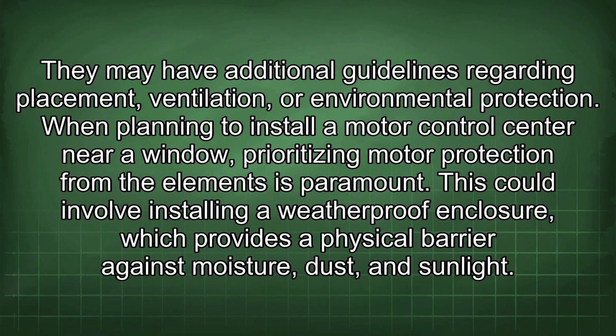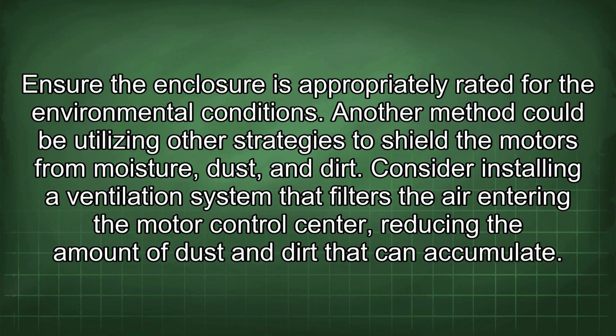When planning to install a motor control center near a window, prioritizing motor protection from the elements is paramount. This could involve installing a weatherproof enclosure, which provides a physical barrier against moisture, dust, and sunlight. Ensure the enclosure is appropriately rated for the environmental conditions.